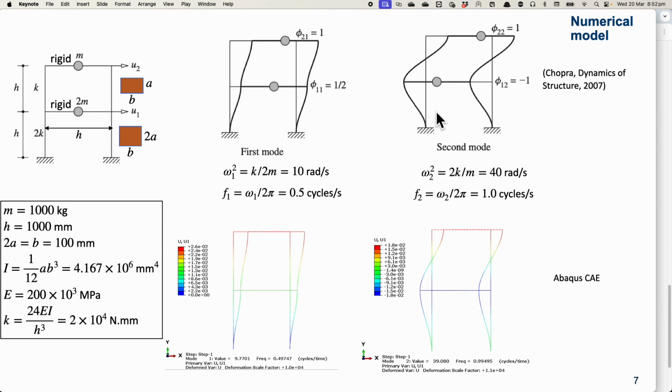Now we will go to Abaqus again to try to do some other cases. Here we have made many assumptions about things like the rigid body. For this idealistic scenario, we could compare our numerical results with the analytical solution provided in the textbook example. Now what we will do, we'll remove these assumptions like the rigid body and, instead of lumped masses, we'll specify the density of the material, for a realistic scenario.